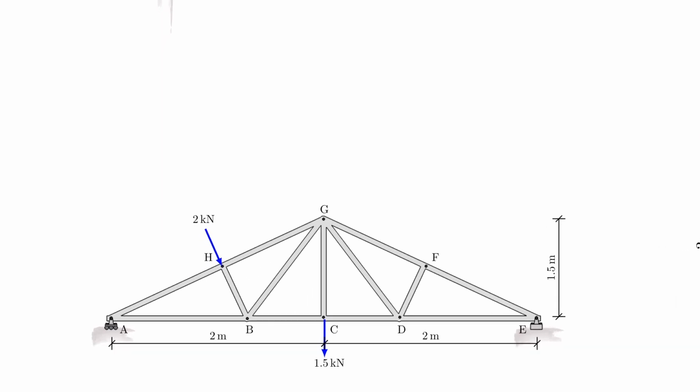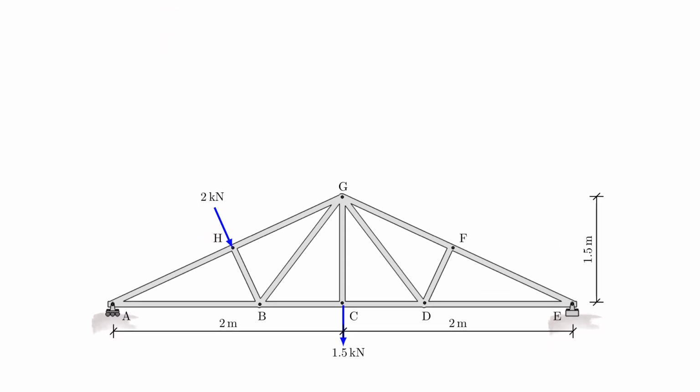Let's take the one here on the bottom. So now what do we have? Here we have two parallel forces and a random third one, but be careful now, there actually is a load now. So this cannot go to 0, right? If this would go to 0, this node would just not be able to resist the 2 kilonewton that's acting on the structure. So here, be careful. That is not a zero force member.